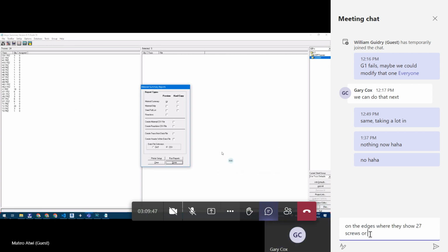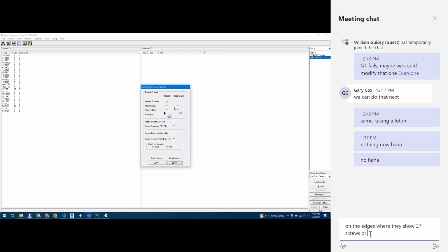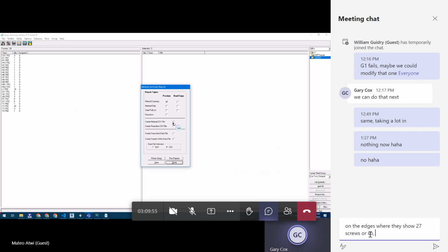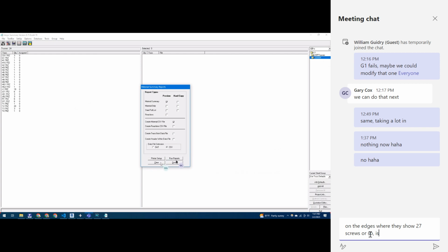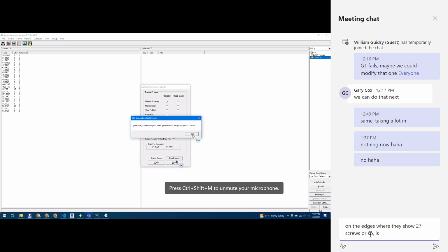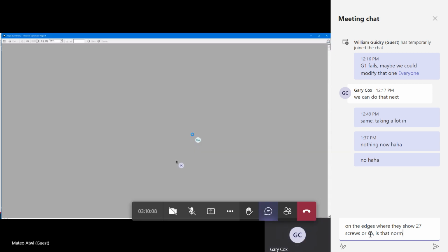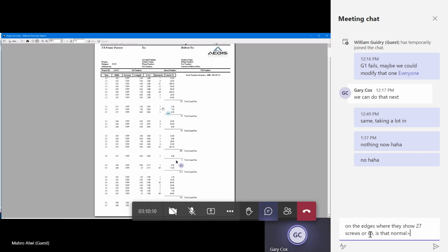So in here, it's loading all that. You have a material summary. There's a couple of things in here you can grab. You can also create a CSV file for them. When you're ready, you'll click Run Reports. You get to tell it where to put the CSV file.